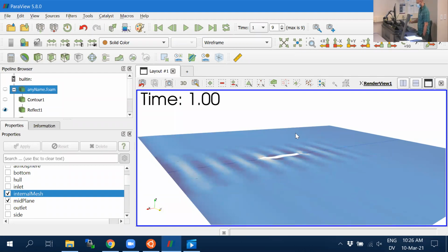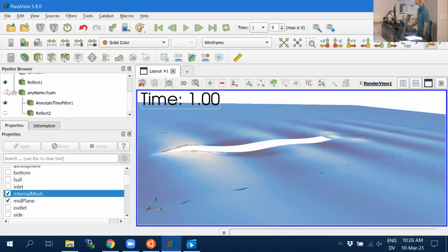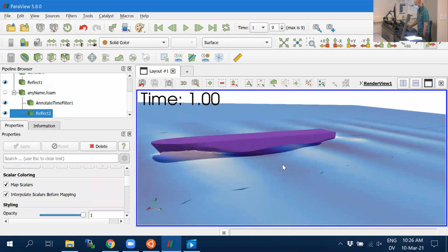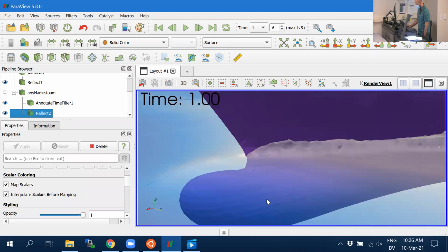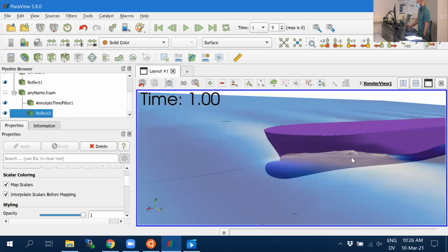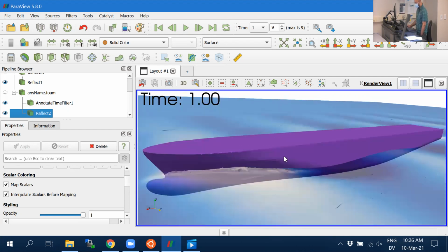But a hydrofoil should work fine. Look at this, we had our bulbous nose here, and that affects the flow and the pressure distribution. So anything that's fully submerged, if you have a nice airfoil, it should generate upward lift. If you create a planing hull, you should get the planing effects. That's why this 6 degree of freedom option is very nice.